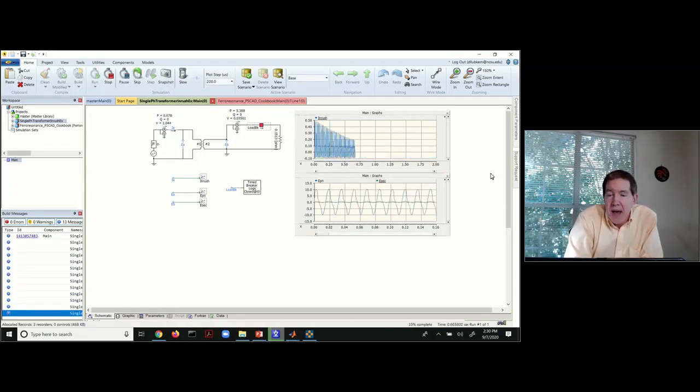You can see that as far as the inrush, the current starts really high. In steady state it would be 0.1, but here at these very high values it jumps up all the way to 0.5. And then you can see what effect this has on the voltage, because this high current with a lot of harmonics means I get a drop across the transformer, which introduces harmonics into my voltage.